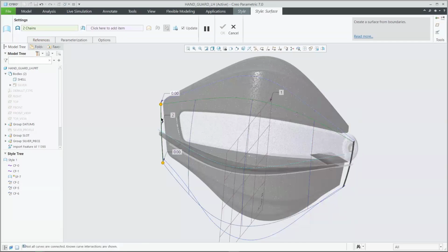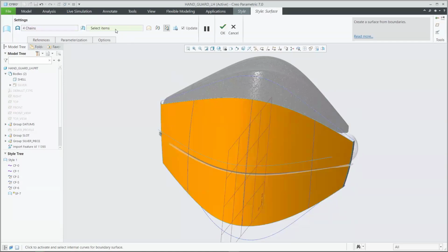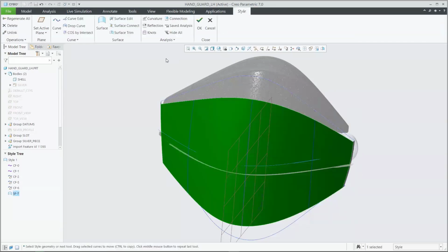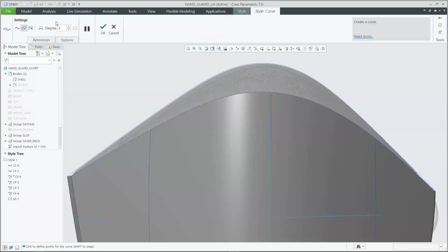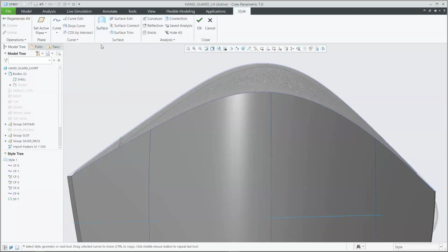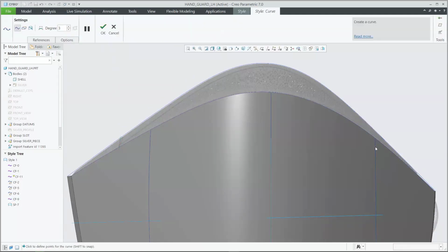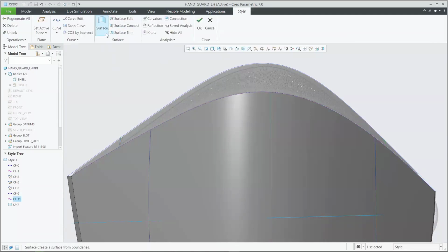Once we have a good amount drawn out, we can go ahead and define our surfaces. We can decide if we're doing a boundary surface. We can even set controlling curves to really define exactly where that boundary or that control is going to go, ensuring the smoothness is there, or helping even to transition from one surface to another. We can do all of those different capabilities inside of ISDX.